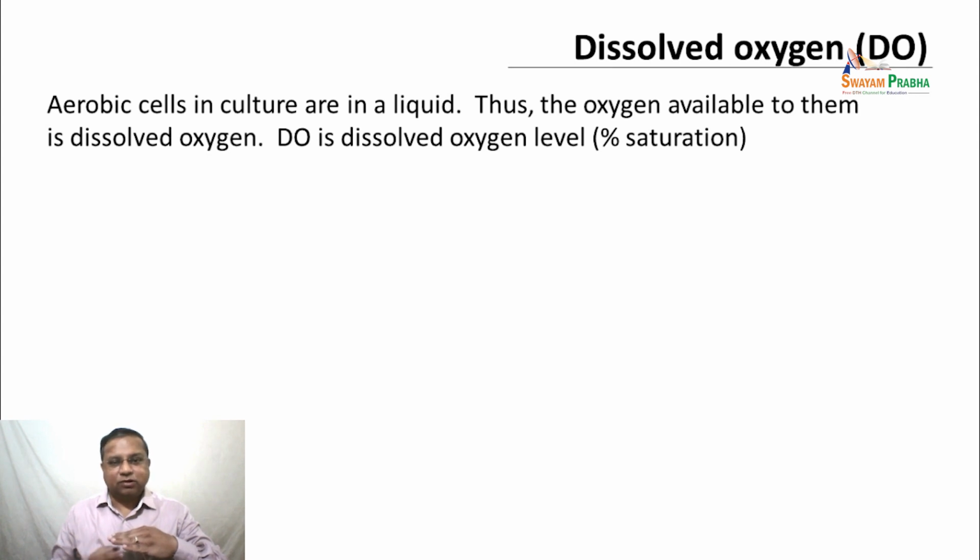In water, oxygen is a sparingly soluble gas. It's only about 8 ppm. 8 milligrams per liter is what you find here when you have 21% oxygen in the air. This is true for any species that is partitioning between two phases, from thermodynamics. You would know this. This particular system is what is of interest in bioreactors. Therefore, we'll look at this in some detail.